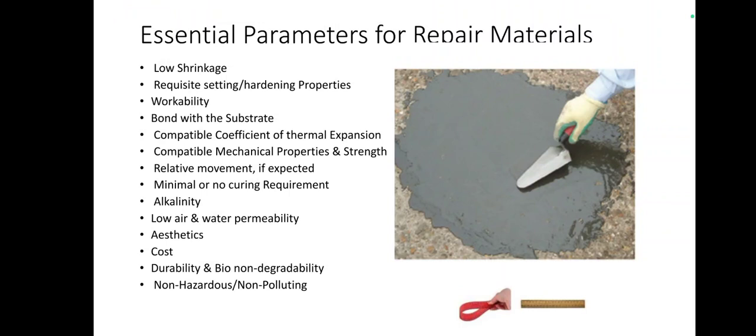Nowadays an excellent material called styrene butadiene rubber, SBR. Many cement related companies are manufacturing it themselves, and standard chemical companies are also producing this SBR. It is a major all-rounder, and it can be used for all repair works, like waterproofing and as a bonding agent, and many other things.